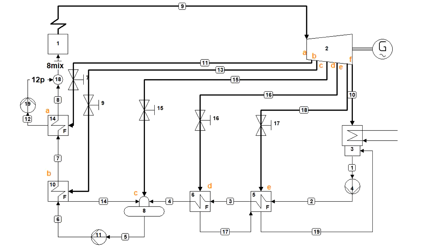In this configuration, it's not feasible to cool down our condensate to have the minimum temperature difference of the heat exchanger at the low temperature side, but rather keep the condensate at the saturated level, which we will show shortly on QT diagrams.